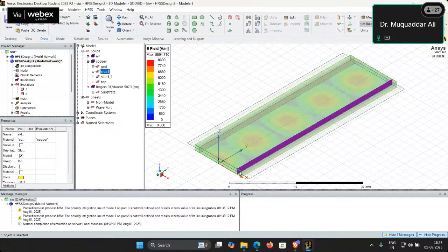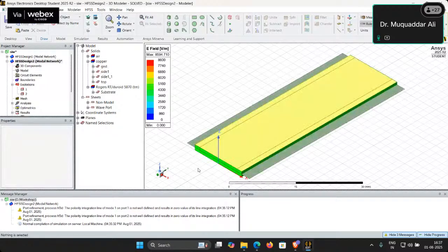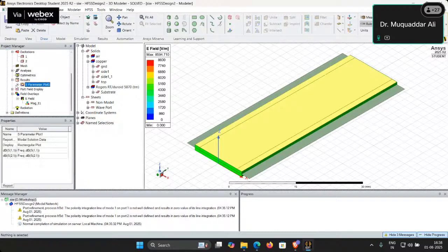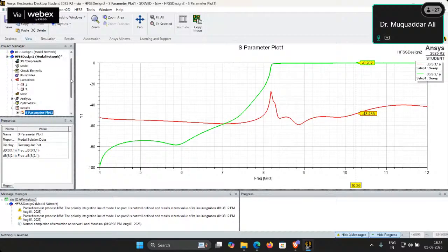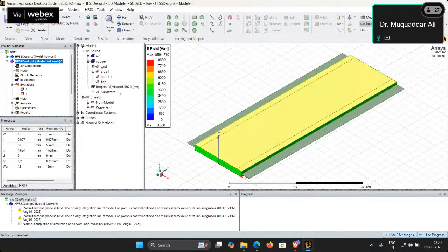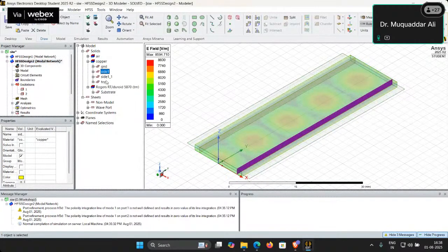Okay, so that is why we first analyze the effect of a thick dielectric filled waveguide with very thin height. In that case also we can see that the waveguide properties are there. It is giving isolation, and due to the dielectric losses there are some losses. Otherwise the waveguide is working perfectly fine. So a dielectric filled waveguide with very thin height will work perfectly, but we are left with the problem of how we can implement these side walls. This is the only problem we are facing.